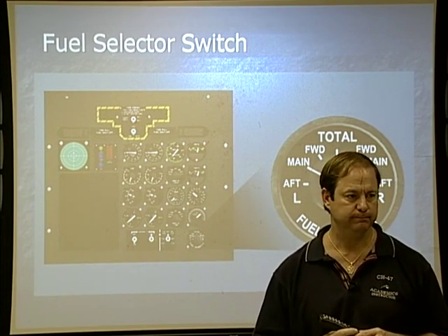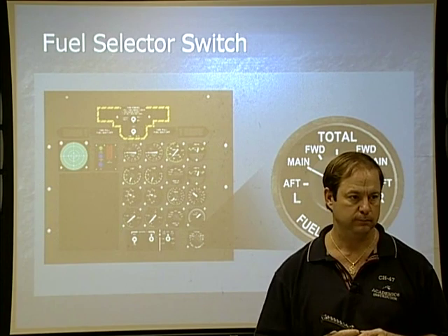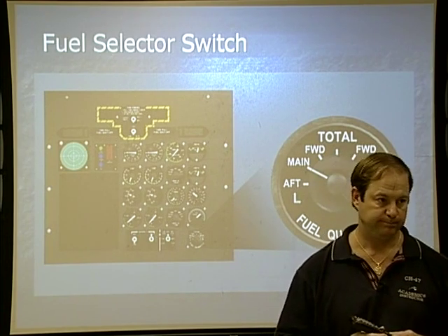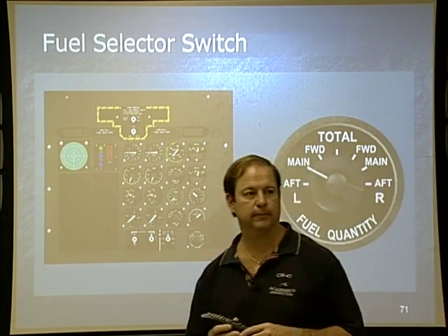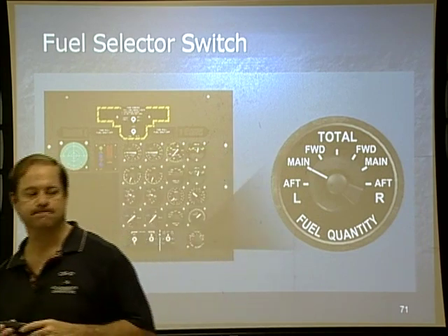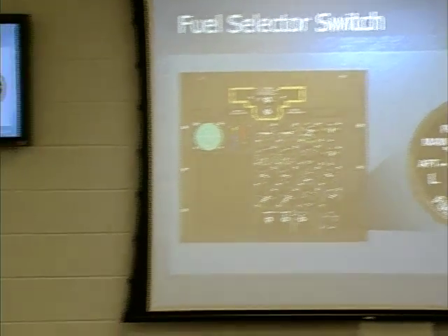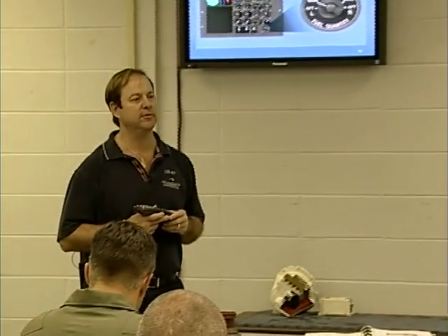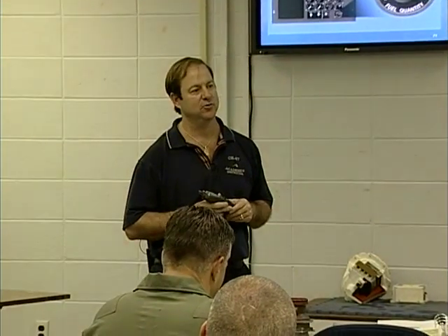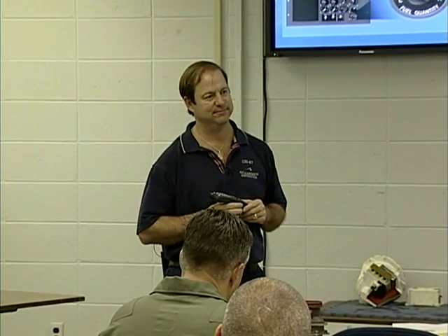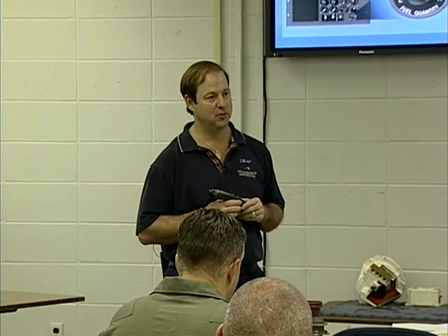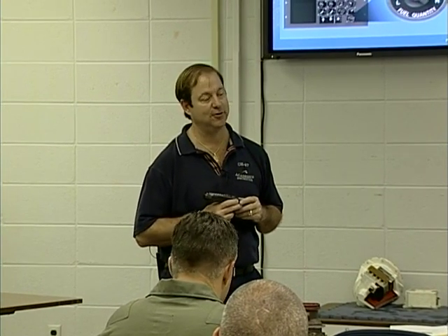You got a question? Nope, they're all AC powered, so you can't see what's on the aircraft until you apply AC power. Yes, sir. Not even the one outside. Which means we're going to end up talking about a what? Because I know that I can refuel this aircraft with just the battery plugged in. But as you just pointed out, both the totalizer and the fuel quantity indicator are AC operated, 115/200 volts AC.